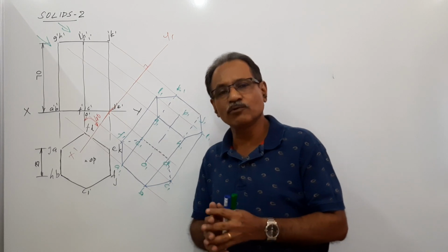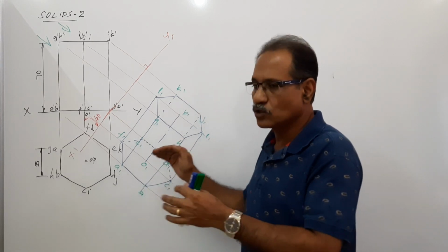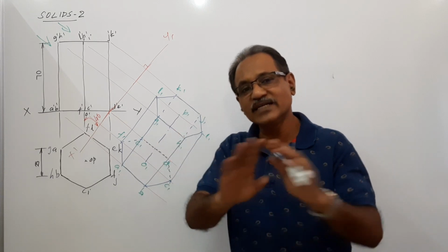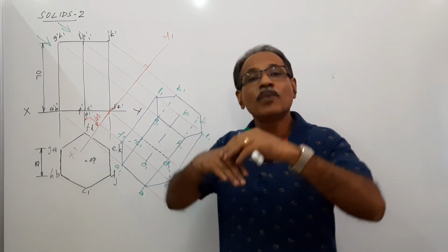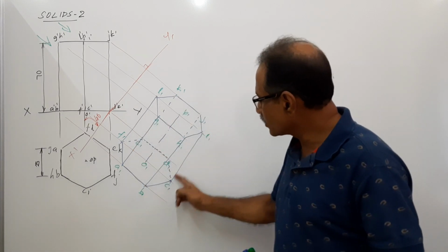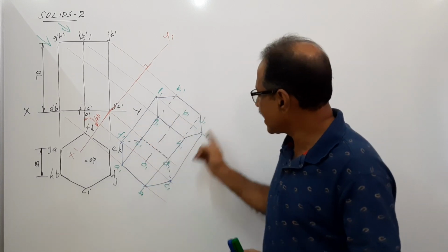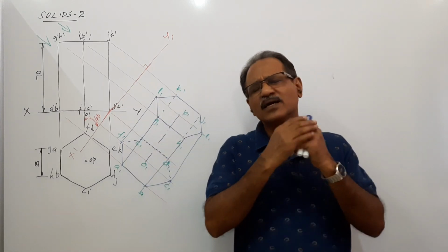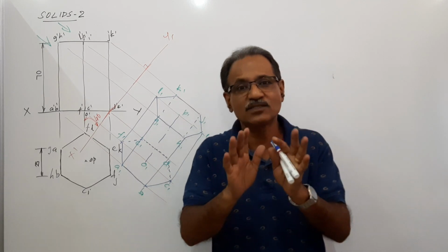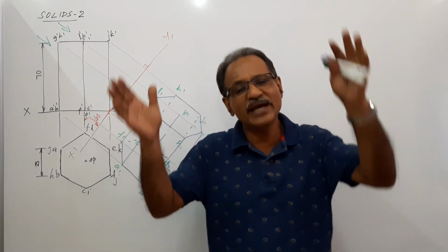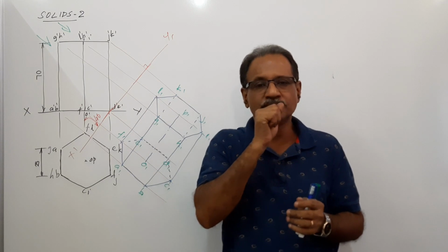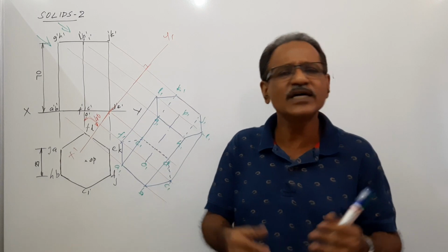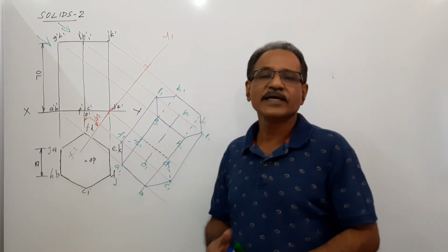One thing which you have to remember while drawing a new view, here the auxiliary plan is drawn. Make all the visible edges firm and all boundary lines firm. This is a physical boundary CL and this is a physical CI. This is a physical boundary FL. Boundaries will never be dotted. So first of all, make all visible edges for which you are sure firm. Then make the boundaries firm. Then you will know which are invisible. Those invisible you will make dotted. That's the procedure of drawing.